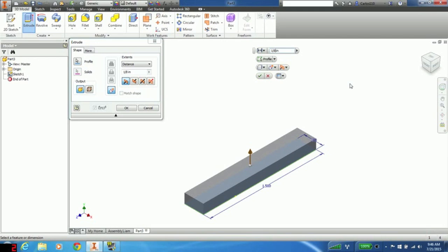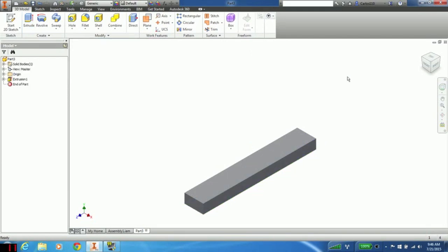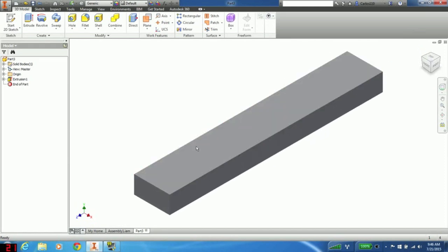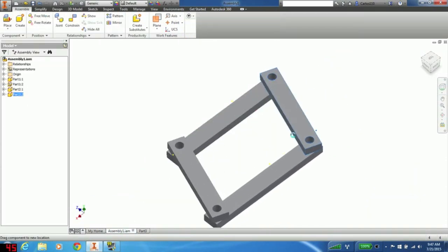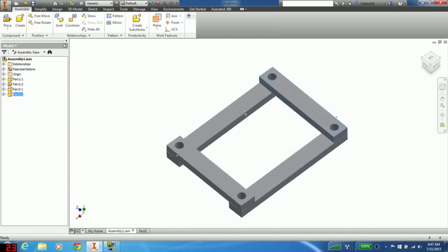You don't always have to do decimal points. So I can type in 1/8 or I can type in 0.125. I'm just going to go with 1/8. So then I can hit Enter and it will finish off the shape. And I can use the Home button to center the shape and center the axes. So now we have our basic rectangle. But you might notice that we're missing the 2 holes for each side where we can finally lock around the axes to create the rotary motion.